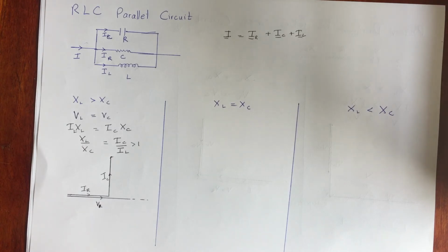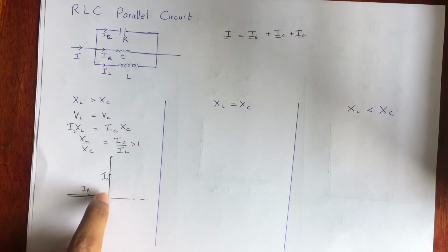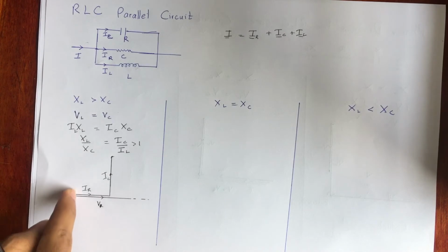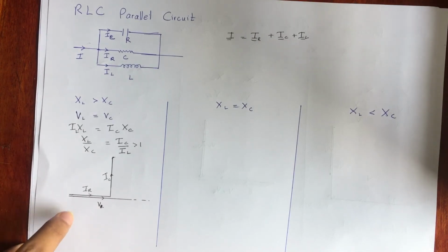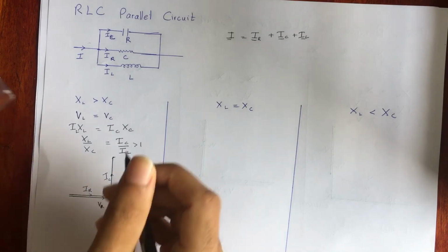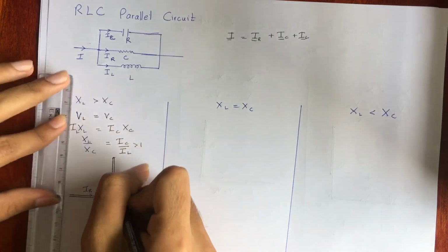The voltage is going to lead the current by 90 degrees in that inductor, which simply means the phase of the current through that inductor is going to lag the voltage phase. So we can directly tell, don't remember these two. If you forget these two, we can tell the I is going to be in the minus y direction because the I is going to lag that voltage. In other terms, the voltage is going to lead that current. So from that we can directly tell it's going to be in the downwards direction.